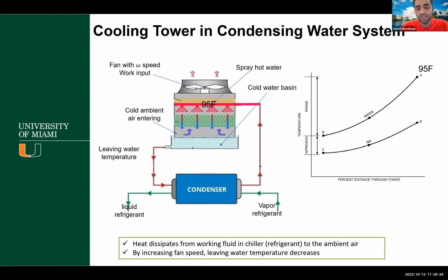This heat is dissipated to the water, making the water temperature, for instance, this is a standard temperature that we are talking about, 95 degrees Fahrenheit. We use a fan with a specific speed that sucks the air inside the cooling tower and directs it to the outside of the cooling tower, right?